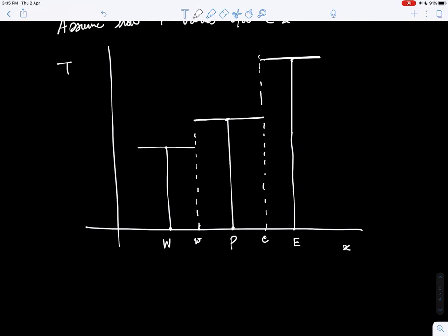So this looks like a very good approximation, except that it would lead to a situation where the value of dT/dx is not defined at the control volume faces, because the temperature shows a certain jump from here to here, and that is not defined. So you cannot calculate dT/dx at the boundaries of the control volume.